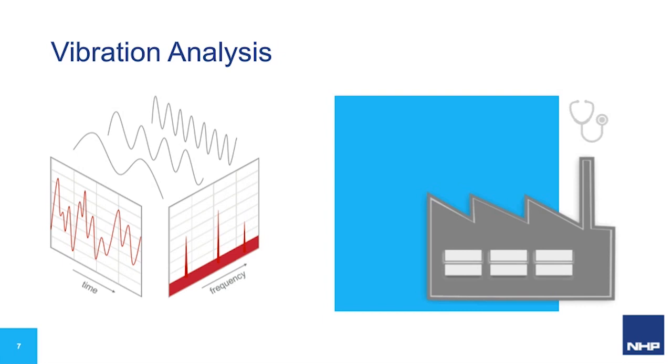Shown on the screen over here, on the left-hand side, the raw time waveform essentially contains all of the popping sounds combined into one raw time waveform. And the process to go from the left-hand raw time waveform to the right-hand frequency spectrum is carried out by using some really clever maths called a fast Fourier transform.